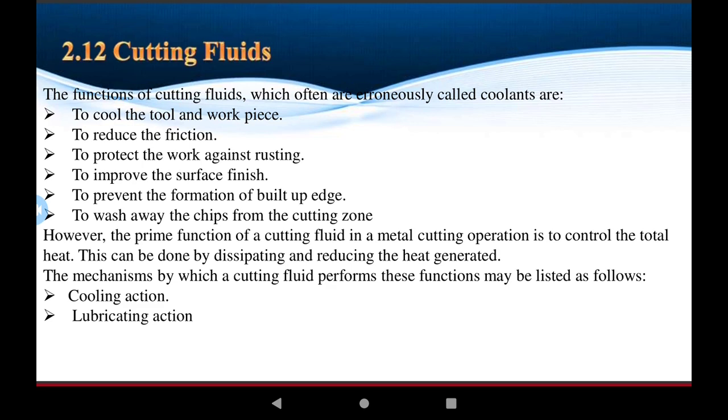the tools and workpiece. However, for the chip formation, heat is generated in two zones. The first is the mechanical energy. The first zone converts the mechanical energy into heat, and the second zone also generates heat according to friction, and friction is between the two contact surfaces, the tool and the workpiece.